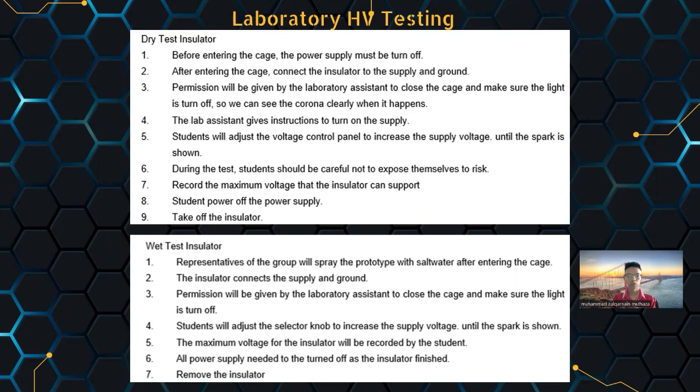Fifth, the maximum voltage for the insulator will be recorded by the student. Sixth, the power supply needs to be turned off once the insulator test is finished. The last step is to remove the insulator.